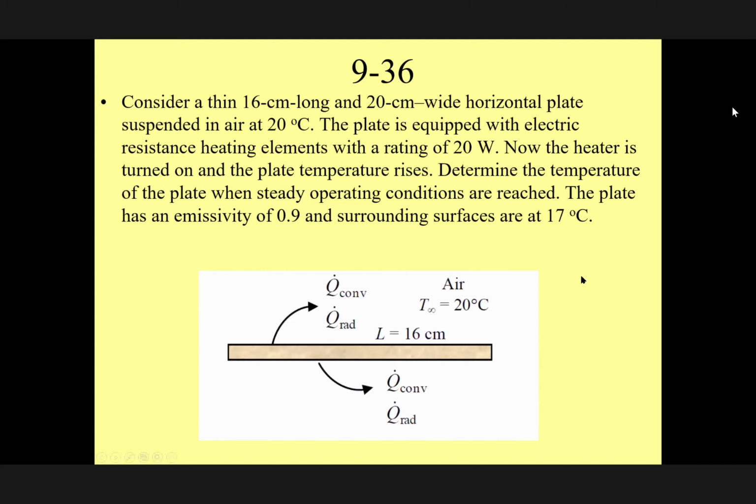The unknown here is the temperature of the plate. I want to see, when I provide 20 watt to this plate and when it reaches steady state condition, what would be the temperature of this plate? And I assume the conduction is too low, so the temperature of the surface at the top and bottom is the same. This is an assumption I'm making, okay? Could you please write the equation, identify the parameters, and tell me what we should do? We have almost 2 weeks left, ladies and gentlemen. Wake up and do it, please.